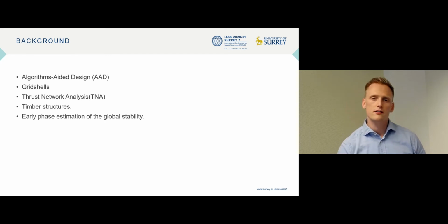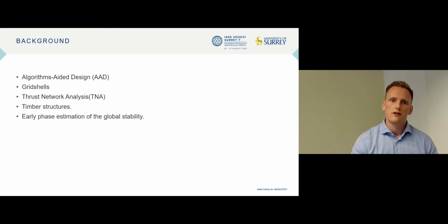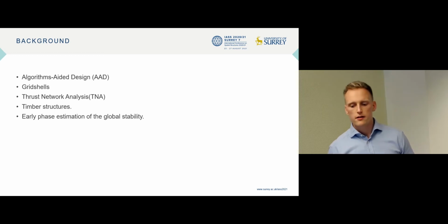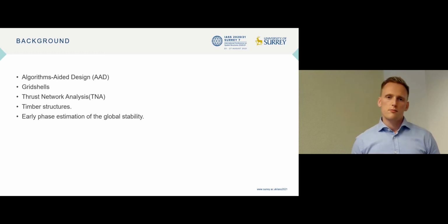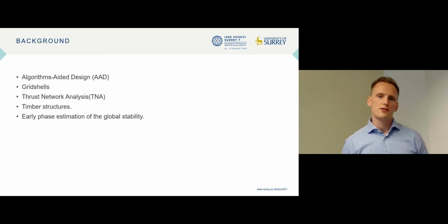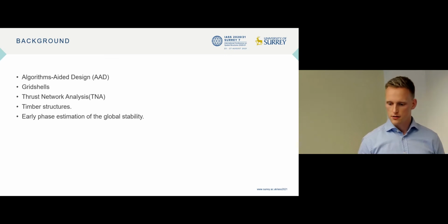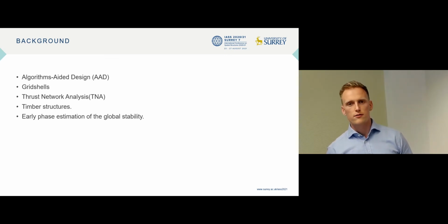And we quickly realized that although several form-finding methods are able to establish a global equilibrium situation for a given loading condition, they do not tell you anything about the stability of your design. Consequently, we looked at providing the designer with feedback on this without having to establish a complete finite element analysis. And this resulted in a plugin for the visual programming language Grasshopper.